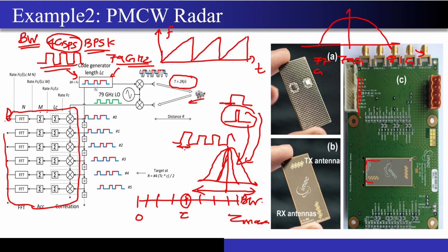Now at the receiver end, you first down convert the spectrum around baseband, 0 gigahertz, but you are forgetting that this higher end is still sitting at around 2 gigahertz. Correct? Now what is the challenge? The challenge is to design the baseband circuit which can process such a high frequency signal of 2 gigahertz.